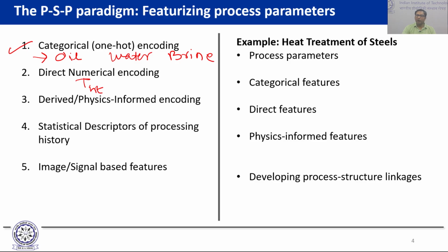So for instance, if you want to know which type of crystal structure might be forming, especially if you start moving into non-equilibrium processing conditions, you might actually want to know what possible structures are there, and then start calculating the formation enthalpies of those structures, maybe start calculating the configurational entropy of those structures, and so on and so forth. So here the value of formation enthalpy, maybe the value of the size of the grains that you are forming, all of those things play into the physics of phase selection.